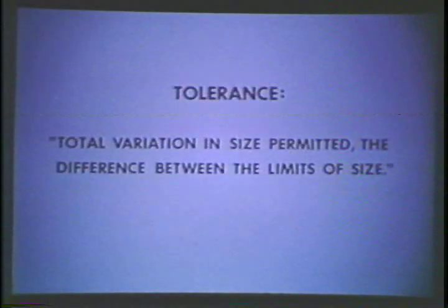If all the parts in an automobile had to be manufactured exactly to dimension, with no allowances made for the slightest errors, the cost would be so high that only the very rich could buy a car. To avoid this problem, engineers permit a certain amount of variation in the machining of parts. This is called a tolerance, and it applies to making threads also.